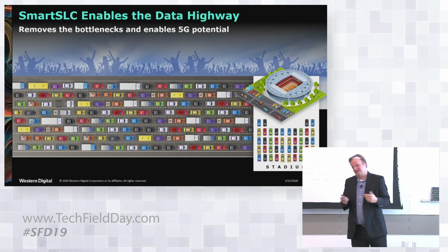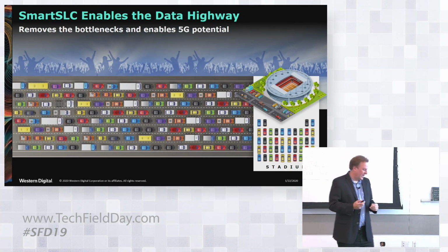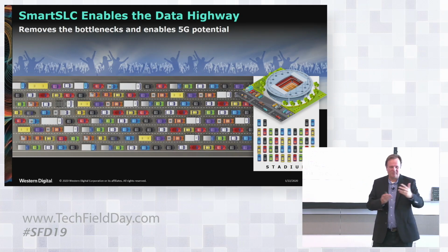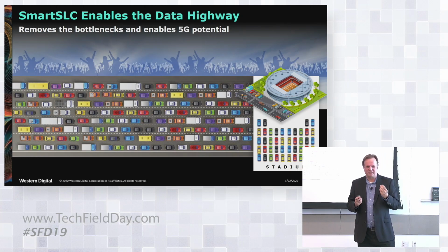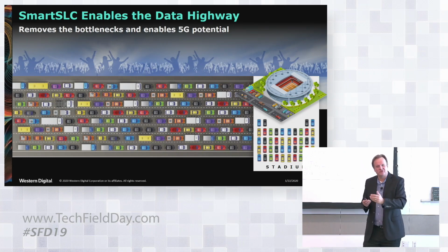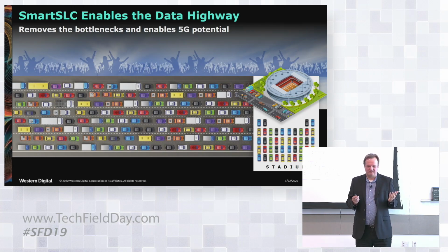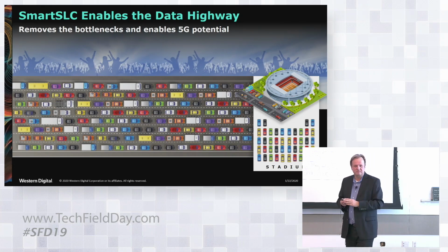It is a hybrid SSD with SLC and MLC and TLC in it, and it is dynamic, so you can partition it differently over time. It is a very creative way of having the long burst throughput of an SLC in a device that has the overall performance and cost advantages of an MLC or TLC. As you can imagine, in consumer devices, as more writing is happening, this is getting a lot of traction, but also in automotive, where people want that SLC performance to guarantee that the data makes it quickly enough into the device. So this is the solution today: at UFS 3.1, it enables full read and full write to maximize that 5G link.